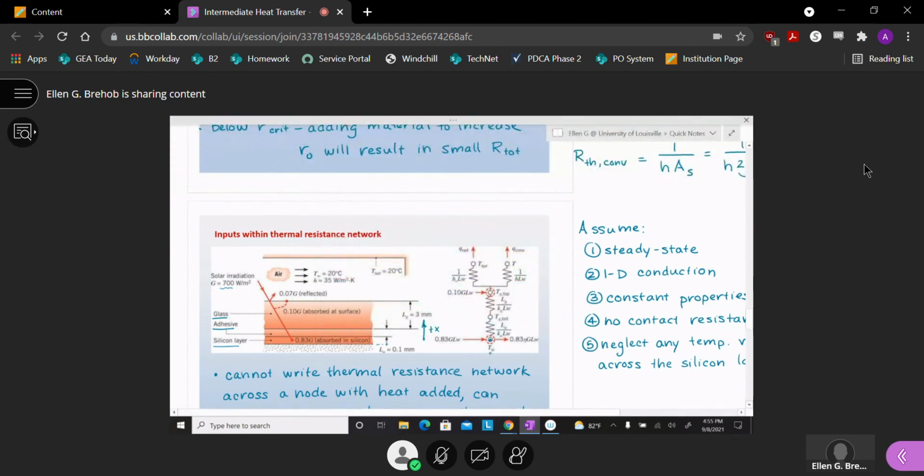This temperature node down here, they're giving us T_Si, and so we're thinking that's the temperature of the silicon. T_G with the subscript G bottom means the lower temperature of the glass. So we went through a thermal resistance element of the adhesive. Now we got the bottom of the glass, and we got the top of the glass temperature node.